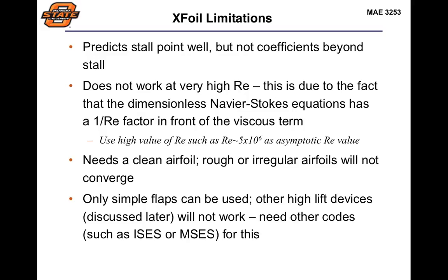So there are limitations to this. Note that it does predict the stall point pretty well. You can go back and look at those previous plots that we showed, but not really the values of the coefficients beyond. That's because inherently stall is a three-dimensional phenomenon once you actually have incipient stall set in. So, once you get into this turbulent regime, all bets are off.